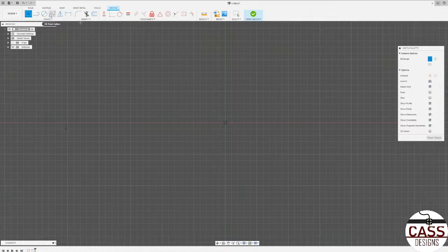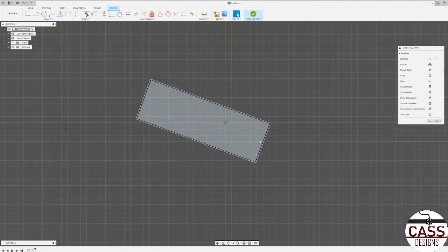All right, so going back to this rectangle. You can see here there are different ways to create the rectangle. You have the 2-point rectangle, which means wherever you click first makes one point. You drag to create the second point to get this rectangle here, and then press Control Z to undo that. The other option is the 3-point rectangle, which is the same kind of thing. You make 3 points to make a rectangle like this. And there you go, you control the parameters that way.